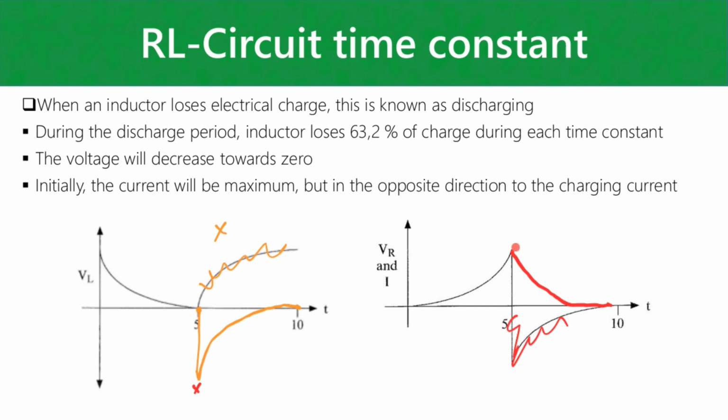And your current is also, so remember the current didn't stop flowing, right? The inductor got energized to its maximum. Now the current is just going to keep on flowing due to the collapsing magnetic field. So your inductor is essentially acting as a source. So your current is just going to decrease as the voltage on your inductor also decreases.